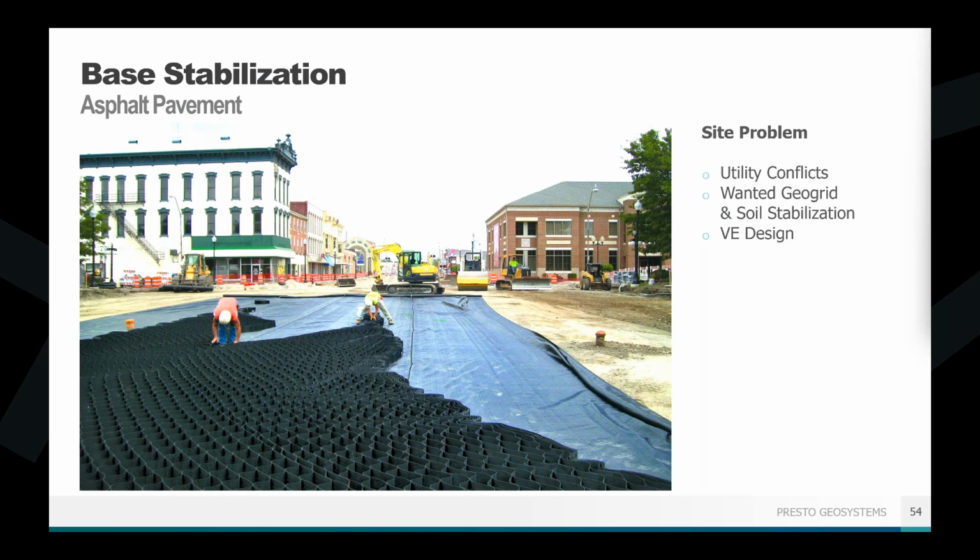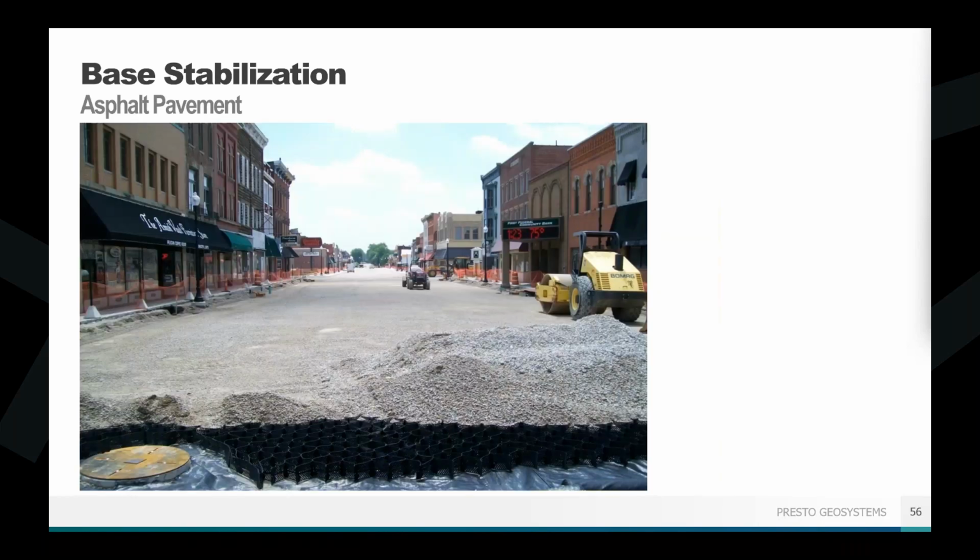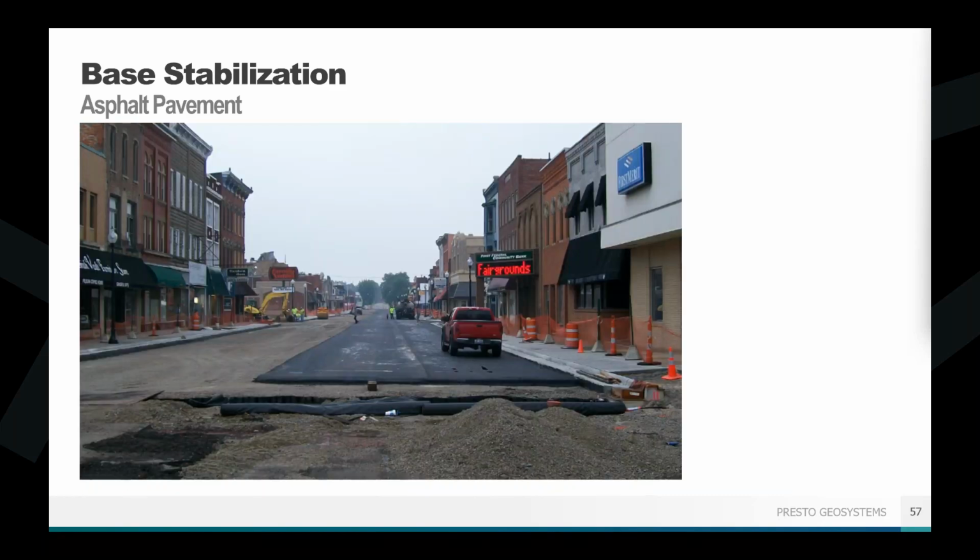In this case, this was a road in Middle Ohio. They wanted to replace their asphalt road, which had been cracking and failing, but they needed a stronger base. So they put the GEOWEB system in underneath it. It's still a very thin base. It's still just going to be the 6-inch deep GEOWEB panels. And then you pave your asphalt directly on top of that. So you can see it filling in with the stone, just as we had seen before. Fill everything in with that stone, and then you pave directly on top of that.